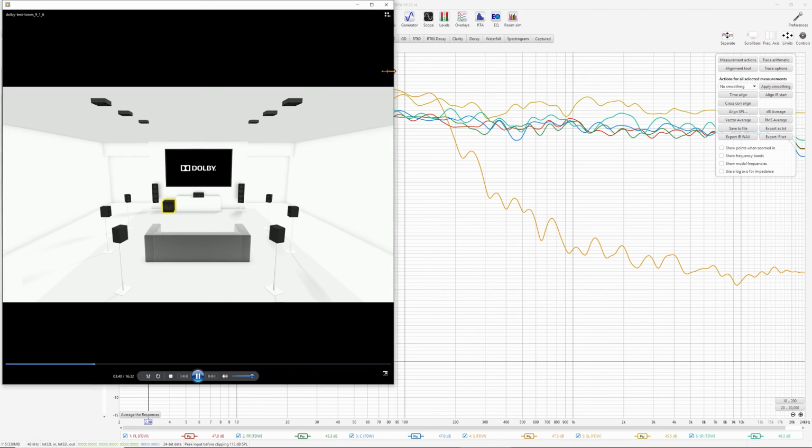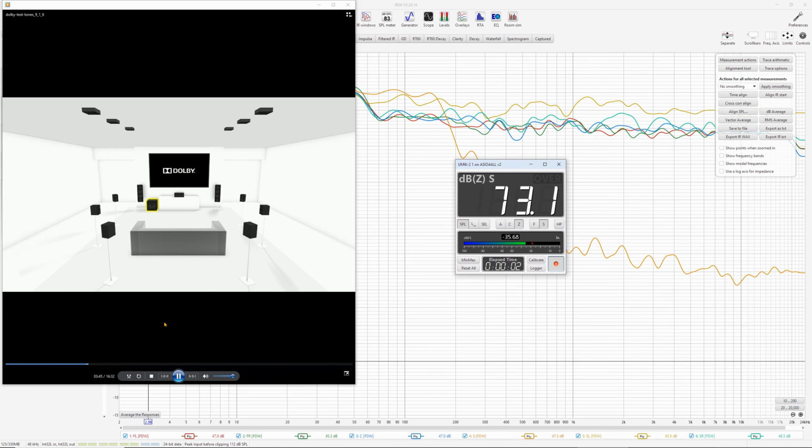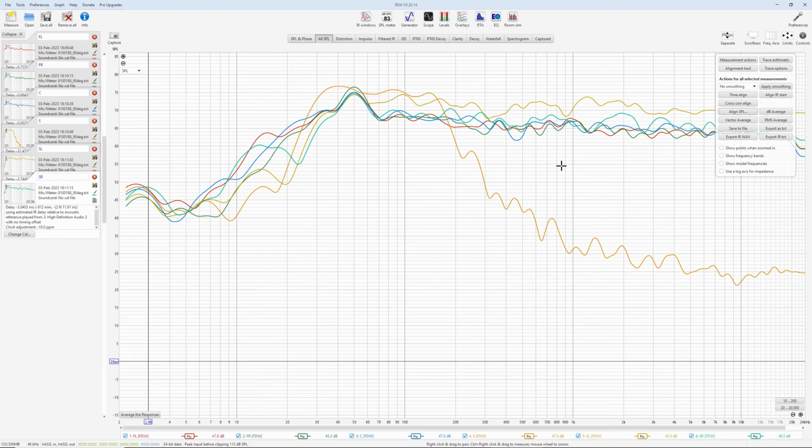And how you calibrate, by the way, is through SPL meter of REW. As you see, it's showing the dB level for the subwoofer right now. And now it's showing the dB level for a speaker I don't have. Yeah, this is what I have. So from here also you can see pretty much full range level. You should maybe do this after crossing over with the subwoofers. It will be even more accurate, because it will really be what this speaker is capable of at the current correction and crossover in terms of all frequencies.